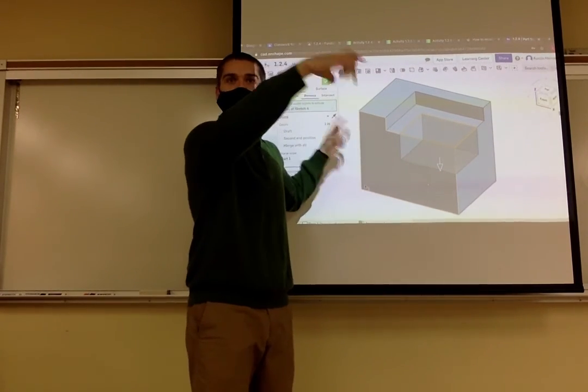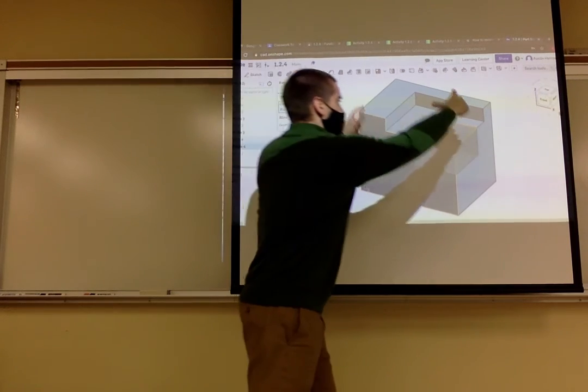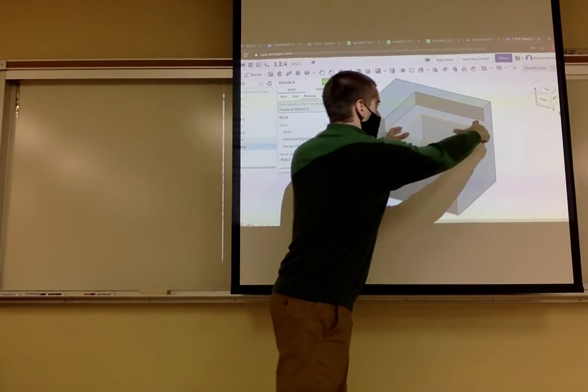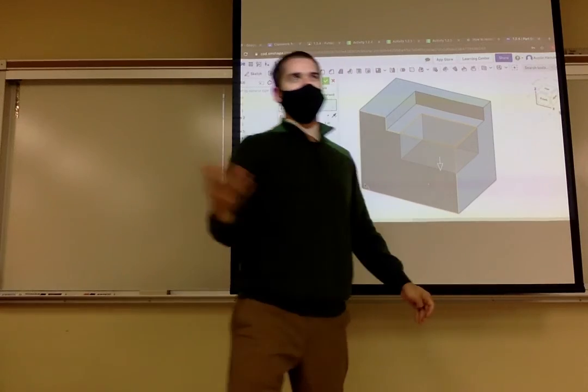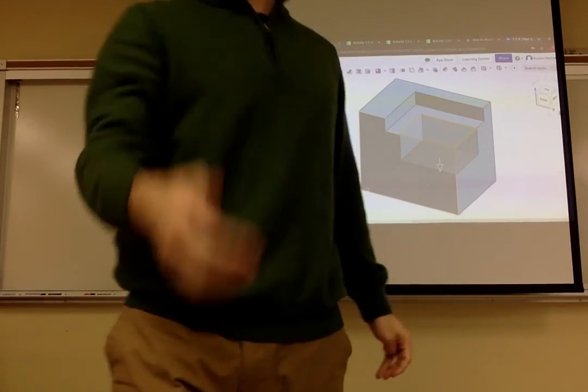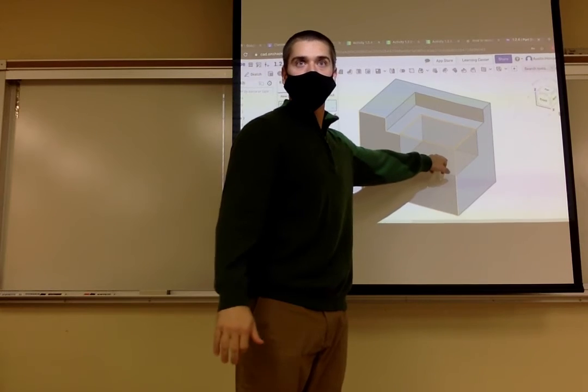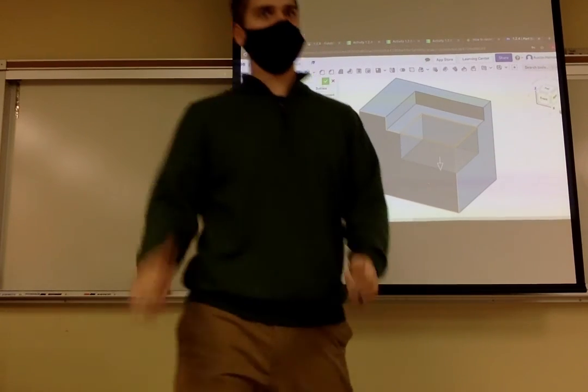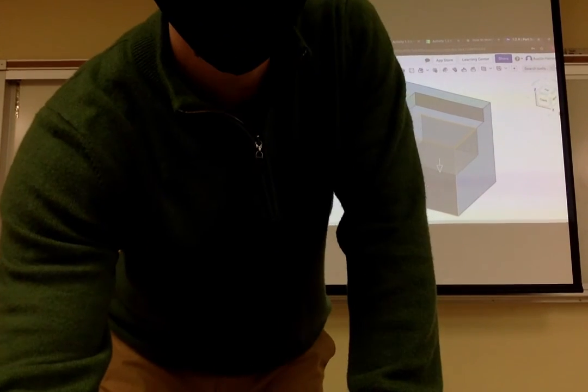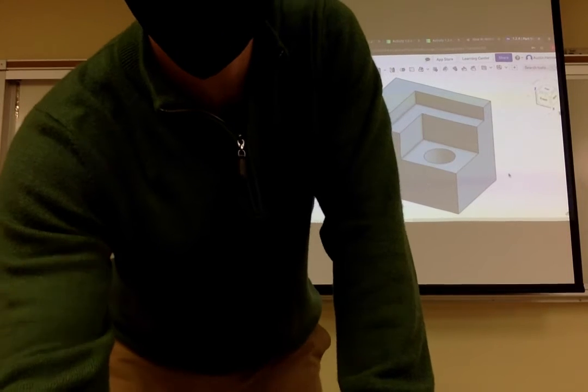Okay. I would make your cutouts and cut the big one first, half an inch. Then cut the smaller one by 0.75, whatever it is. Then you now have a surface. We'll just draw your circle or make your hole and cut that through. So that's the most efficient way to make that part.